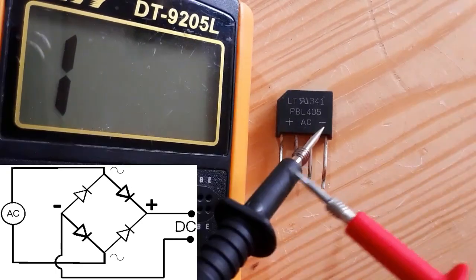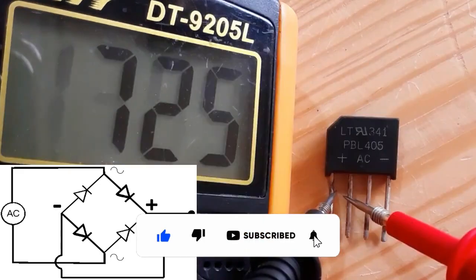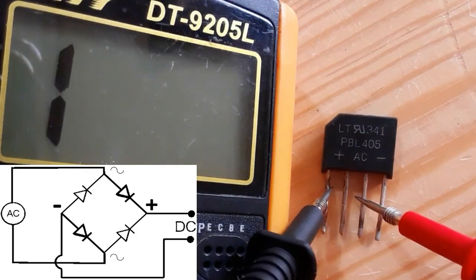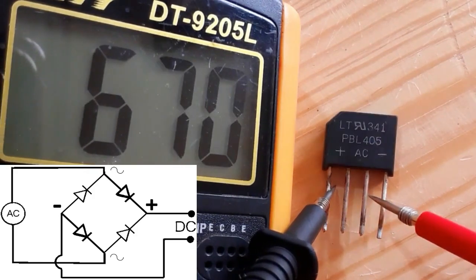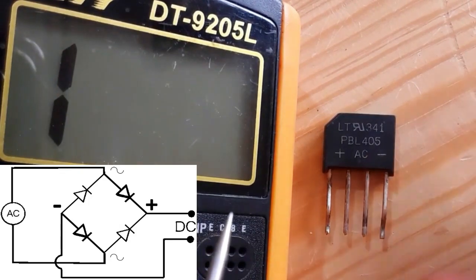You can also check it by putting the black probe on the plus terminal. Here we get a reading of about 600. Here we should get about the same reading, 600. And here we should get a double reading or a double voltage drop. This means this is a good bridge rectifier.